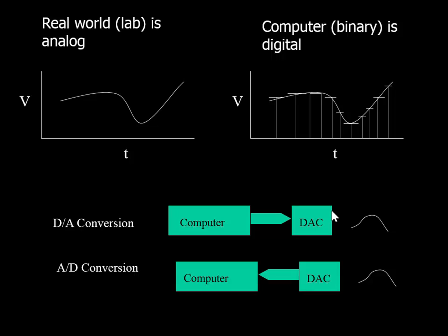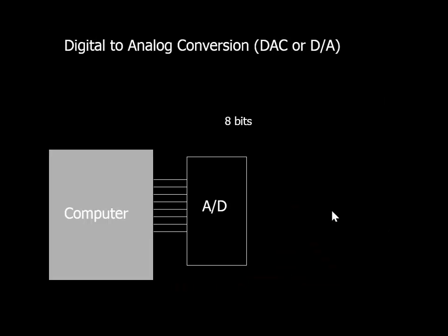If it's above 26 degrees, we turn on the air conditioning. Turning on the air conditioning is a digital signal. It's on or off. When the temperature gets below 23, we turn the air conditioner back off. So that's typically a digital signal. We don't do as much digital to analog, but we do a lot more analog to digital. And if you look at our 8051, it's equipped for a lot more of that.